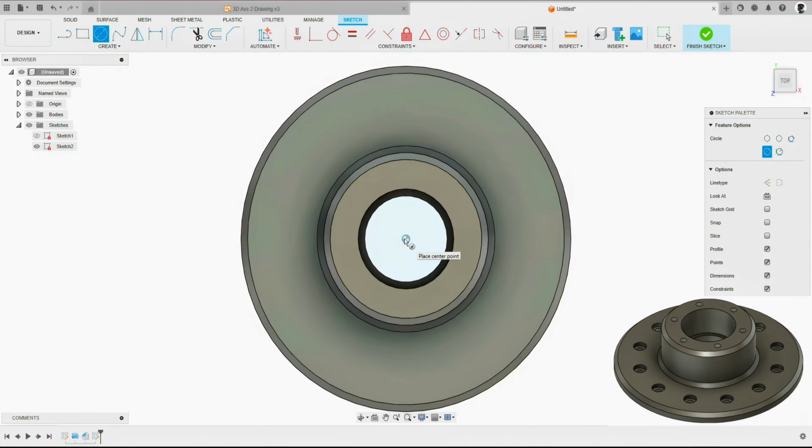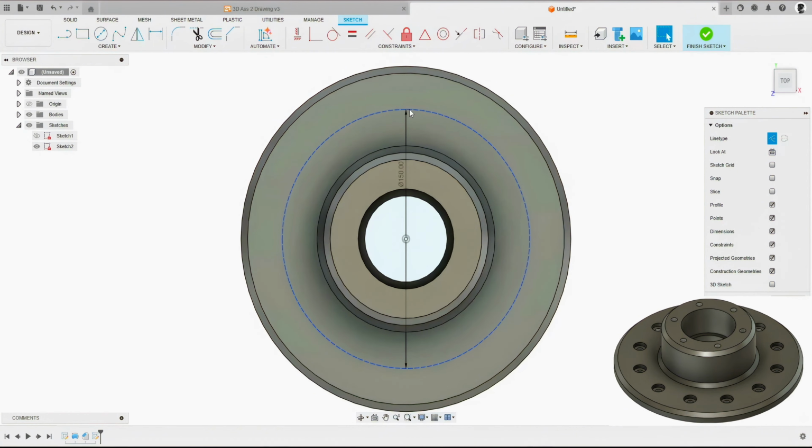So let's start with the circle tool then, and I'm going to input a construction line. It'll be a circle, in fact, and that's going to be our pitch circle diameter. So put 150 mil there, and we know that our 12 circles are distributed equally around this PCD, pitch circle diameter. Remove that dimension slightly.